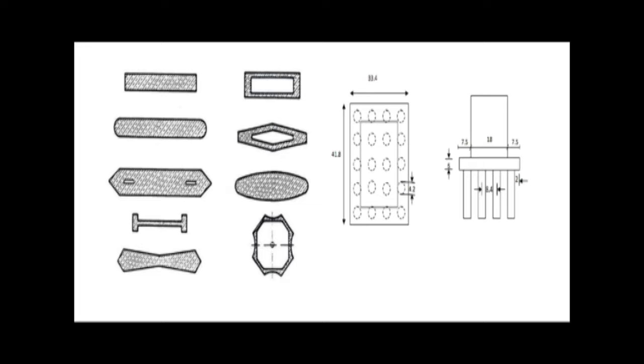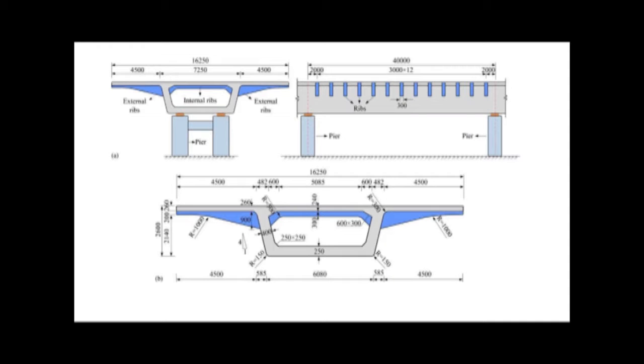So the cross section of the pier is very typical and different, which makes it a different member than the abutment. Though one characteristic of the abutment and the pier is the same, that it holds the upper structure, what makes it different is, first, it's an intermediate support, and second, it faces the impact, the thrust, and the whirlpools you can see are made around the cross section of the pier.